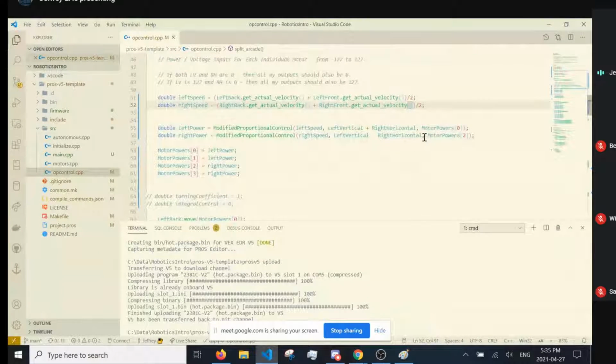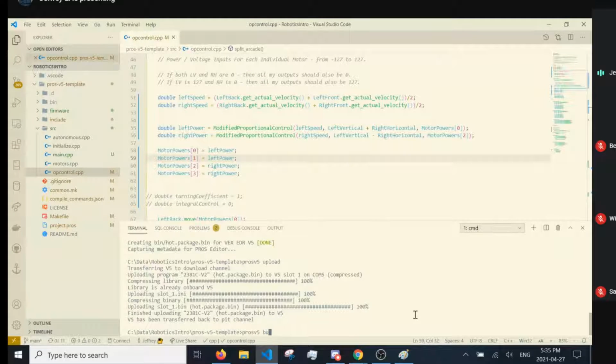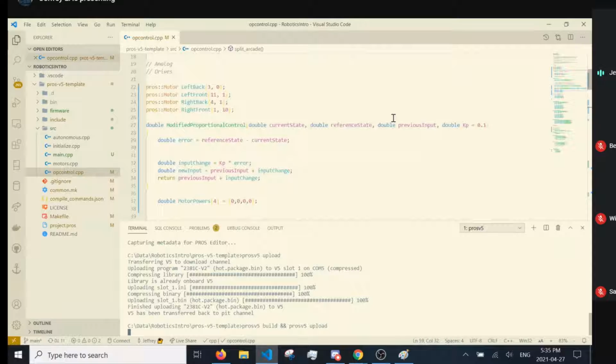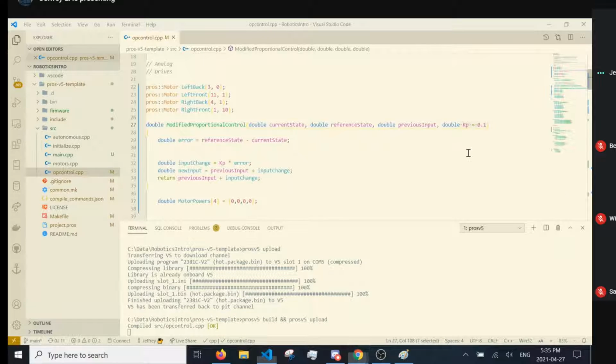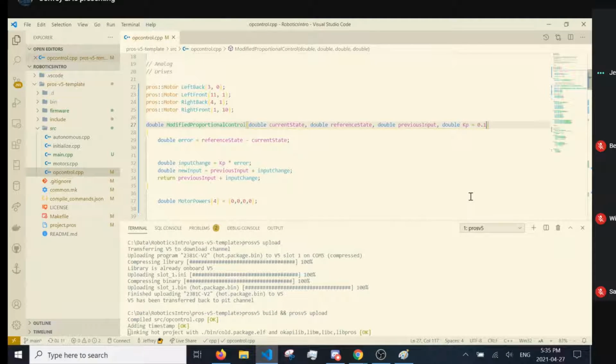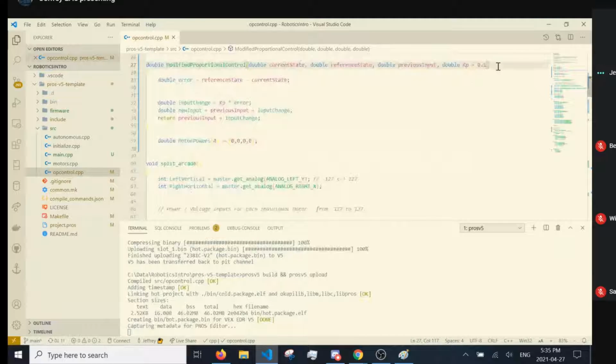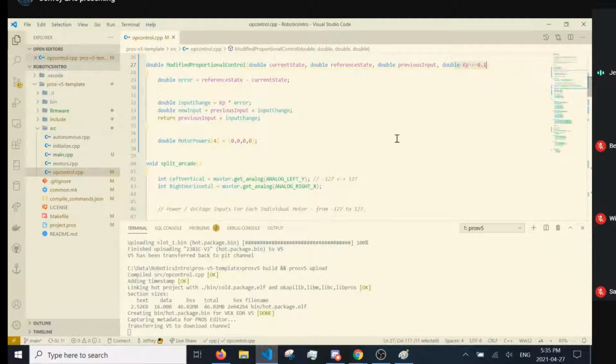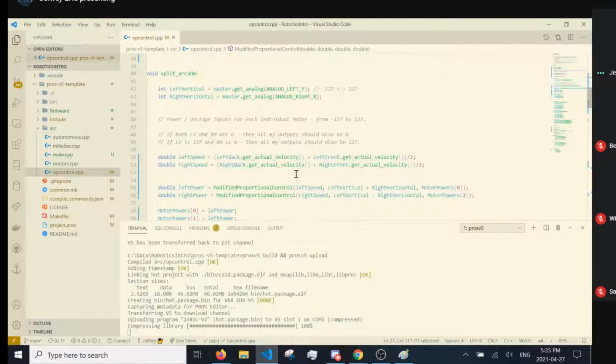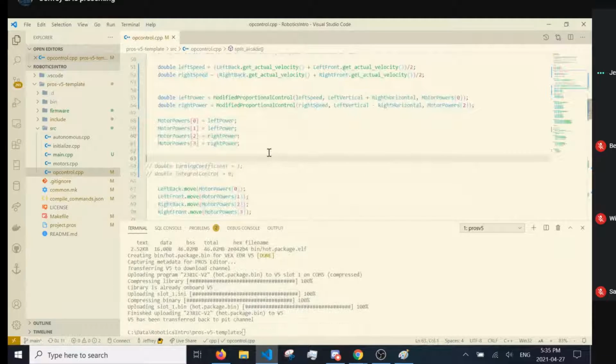Are there any questions about how the system works? That would be a good time to ask. It will just take a second to build. Hopefully this doesn't blow up the robot. There's a chance that if you guess this proportional constant wrong, you'll blow up a robot or something like that. You kind of have to mess up quite a bit. Anyway, if anything weird starts happening, just turn off your robot and guess a lower constant. That generally works. Okay. Should we go first?